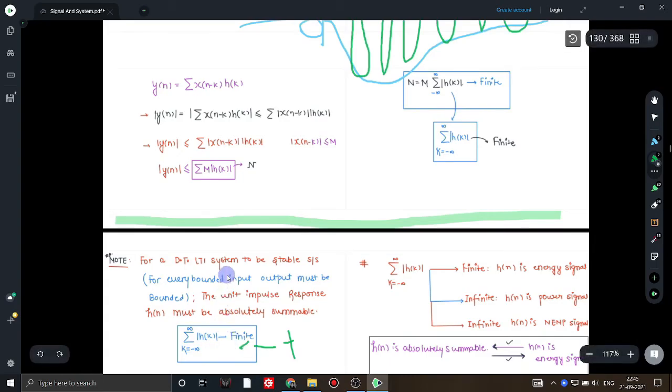In the time domain, if the integration of the modulus of the function is finite, then the entire system is stable, because the integration of the modulus tells us that the function is absolutely integrable, having finite duration. Finite duration signals are stable. Now, in discrete functions, this integration is replaced by the sigma function, that is, summation.